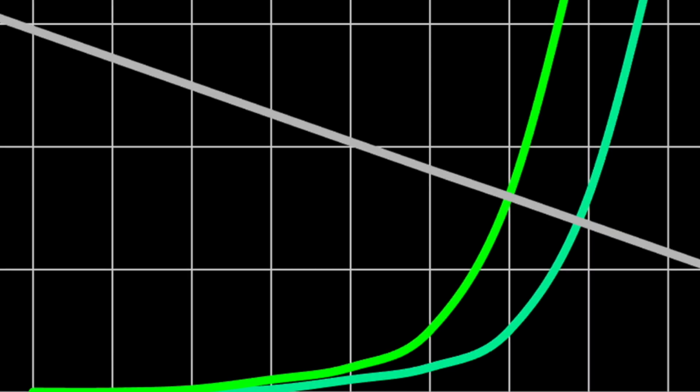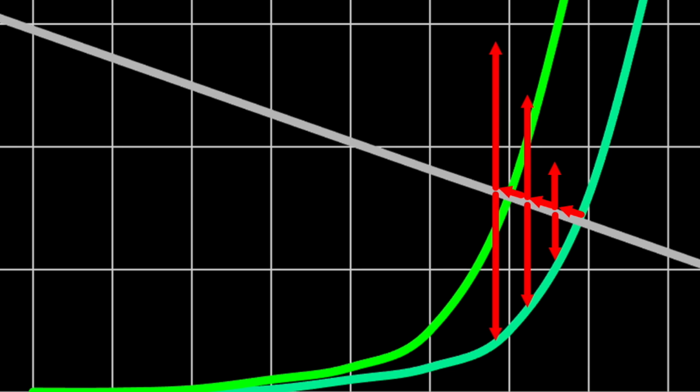Assume we are operating 2 LEDs at maximum current and one has a slightly higher temperature than the other. Then this is causing less current flowing through the cooler LED and more through the warmer one. As an effect of this, the warmer LED gets warmer and warmer, while the cooler one draws less and less current and continues to cool down.